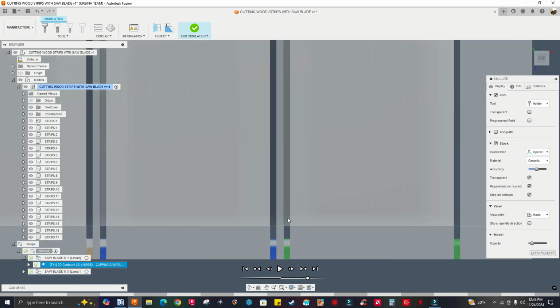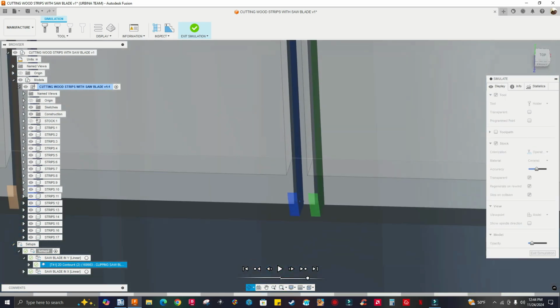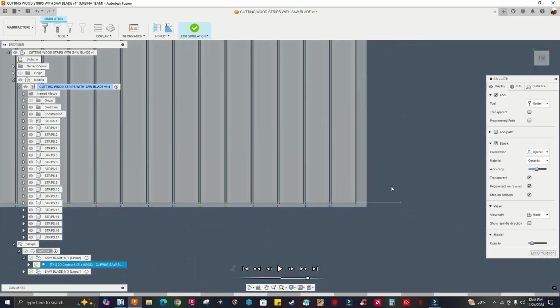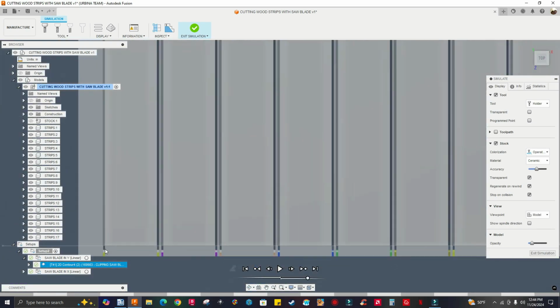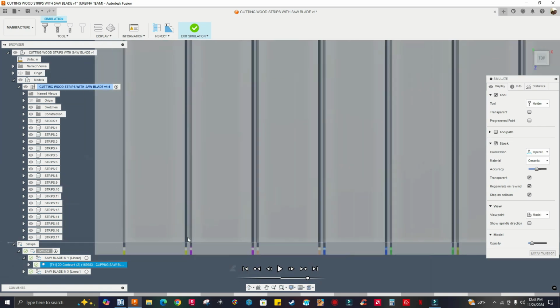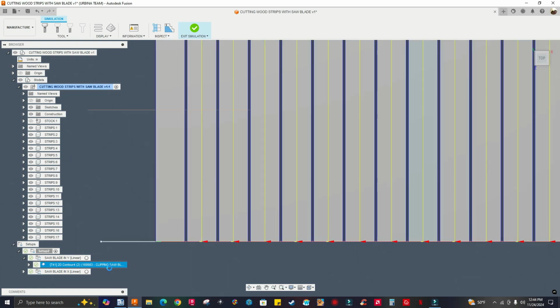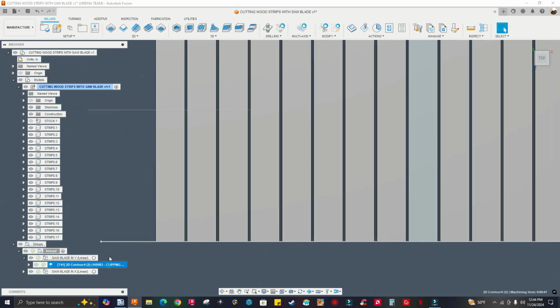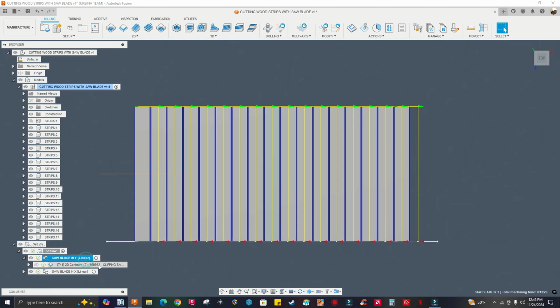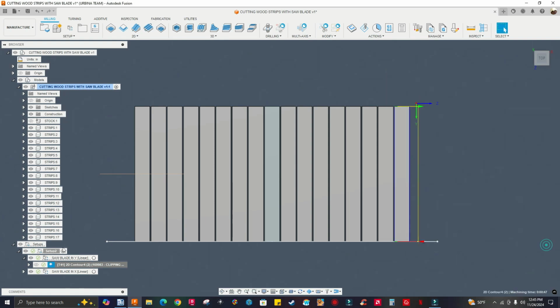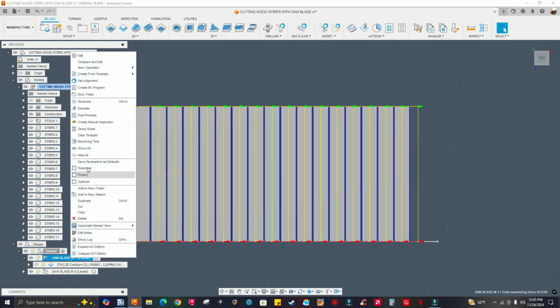Okay, see it's cutting into the material. So I'm going to have to do an offset, just like I did in the first one. I have to offset this toolpath. Remember it's plus 0.18 inches, right? So right click, edit. Let's go. No, actually click on cancel. So Saw Blade Y pattern. Right click, edit.